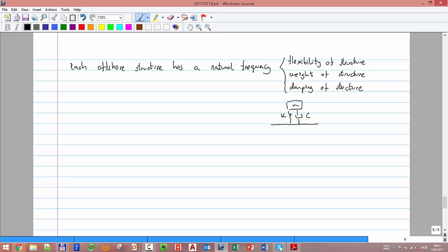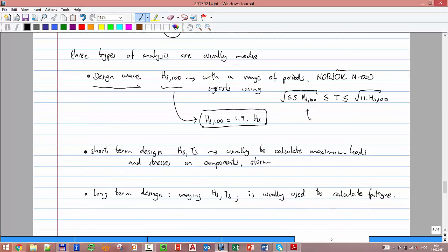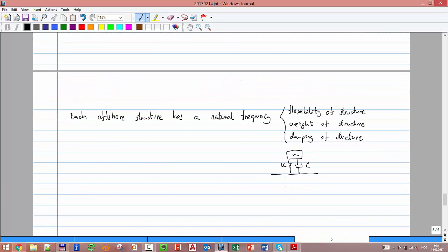To make it simple, you have a phenomenon that is called resonance. Resonance is when you excite the structure exactly at the natural frequency, or very close to it, and you get the highest amplitude possible. I move the bar, I see the frequency, and then I excite it exactly with that frequency. If I do it exactly like that, my amplitudes will be very high. And if my amplitudes are very high, the loads and the stresses are usually also high. Is that clear? That's what we call resonance.